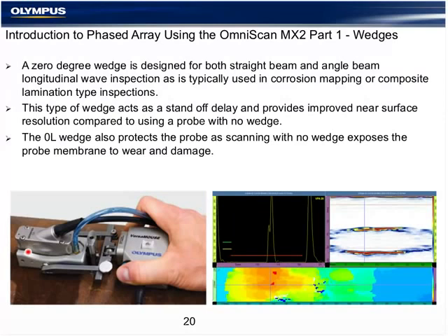The footprint inside the wedge would be about 50 millimeters, and inside that 50 millimeters we have an individual A-scan for every focal law or group of elements. All of those together can collect a C-scan. The S-scan you see here is made up of many individual A-scans. The blue cursor, as I move it from side to side, shows me the same A-scan that it represents.